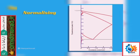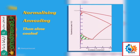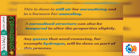In both normalizing and annealing, the material is heated to the austenite range and then slow cooled. This is done in still air for normalizing and in a furnace for annealing. A normalized structure can also be tempered to alter the properties slightly. Any gases that need removing, for example hydrogen, will be done as part of this process.